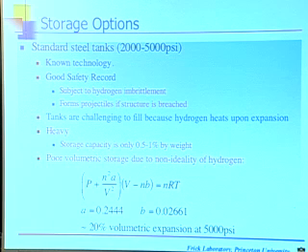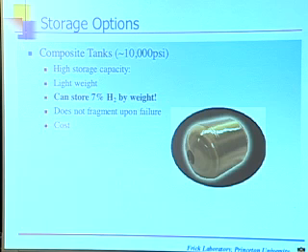The other problem is that hydrogen heats up when you pressurize it quite a bit. And so if you think you're going to pressurize a tank in 2 minutes, you better have a really good way of dumping the heat because you're going to have a very, very hot tank, which probably is not a good idea around hydrogen. So those are issues, but you can see they're engineering issues. One could get around them.